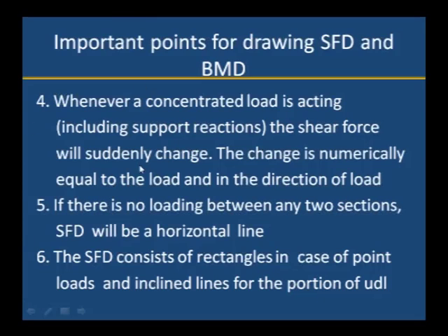Then whenever a concentrated load is acting, including support reactions, shear force will suddenly change. At the point where the concentrated load is acting, the shear force suddenly changes. The change is numerically equal to the load. Whatever the load value, if 10 kilonewton is acting at one particular point, then the shear force change will also be 10 kilonewton, which is a vertical drop.